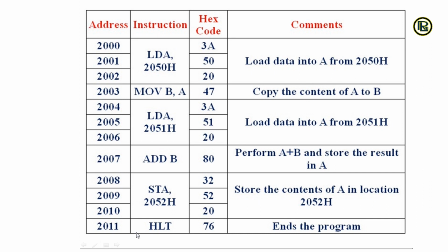And then I have to end the program. For that I have the instruction HLT, and that command has the corresponding hexadecimal code 76, which is written in the memory address 2011. Now let's do the experiment on the trainer board.